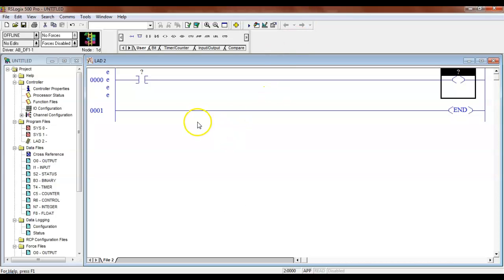And then we have to understand the PLC. What we have on the PLC, if you look at yours, is all these inputs, and beside each one it's assigned a number. We call it an address. So what I have to do is tell my PLC which one of these inputs I want to get information from. I'll start off and say I for input, and then I'm going to say 0/0. Like I said, this is something that y'all won't have to understand, but we have to tell the computer how to select this switch right here.